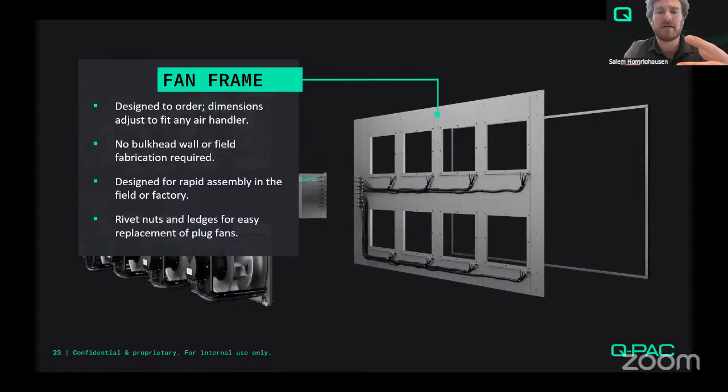And once the existing fan and blower are taken out of the unit, then this is just going to install into that cross-sectional area where it was before. So the way it works is once the first panel goes on, there is a bend in that panel that makes this channel with the next piece that slides into it. And once the two flanges connect, you're just going to shoot your sheet metal screws into the pre-punched holes on the frame to connect them. So it really makes the assembly of the product really easy.